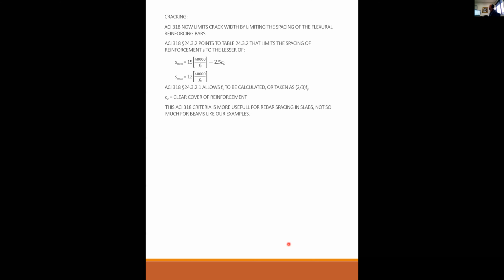Oh, that was the last slide. So let me show you why. For beams, you run this equation here. In fact, we can. Let's do 40,000 divided by, what did we have, 33,000, times 12. And this gives me a maximum spacing of my rebar of 14.5 inches. Well, I've got 6 number 8s in a 20-inch wide beam. My spacing is like 2.5, 3 inches. This is not helpful at all.